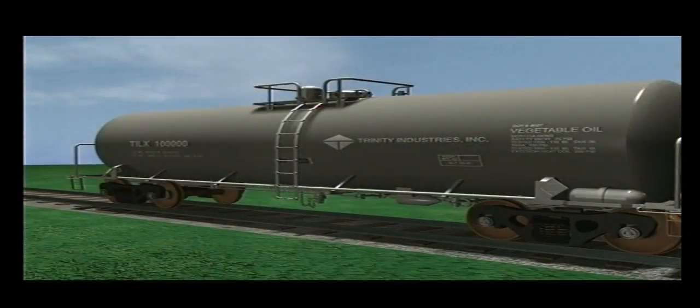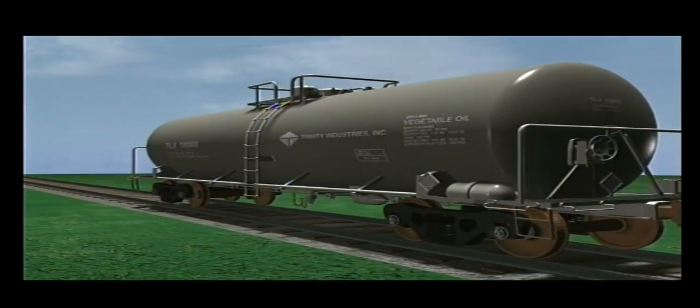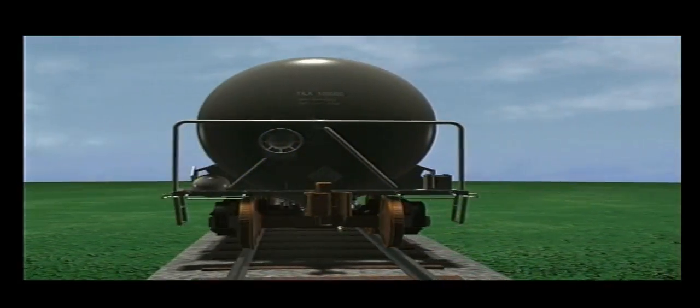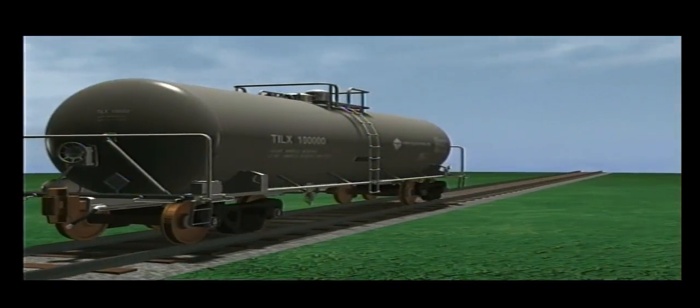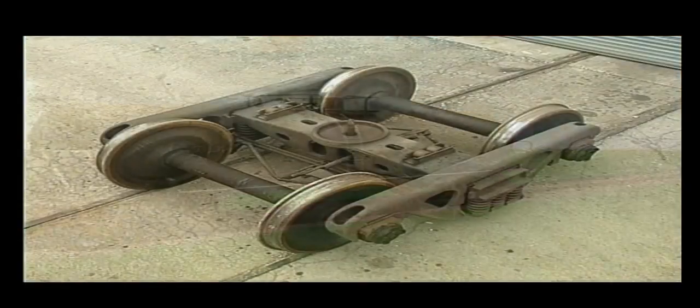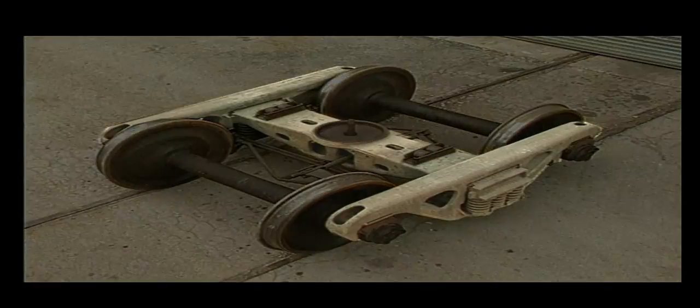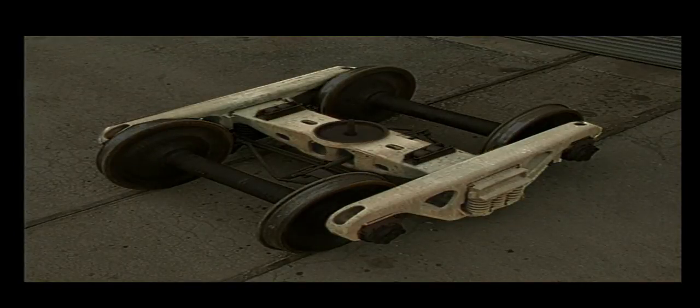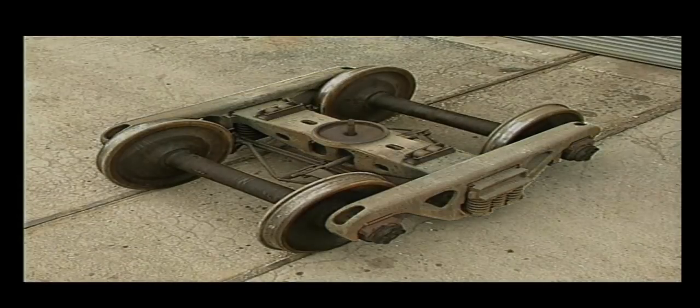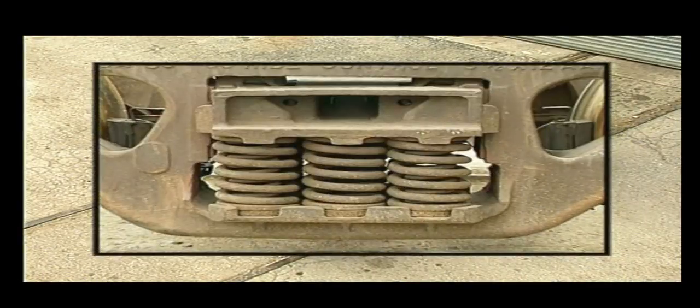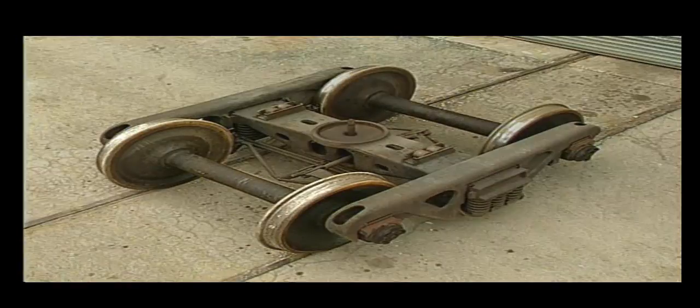These underframes are mounted to the truck assemblies. The trucks, in turn, allow the tank car to be moved along and guided by the rails. A truck assembly consists of the following basic components: the side frames and bolster, which form the framework for all other truck components; the springs and snubbers, which absorb movement between the side frames and bolster;